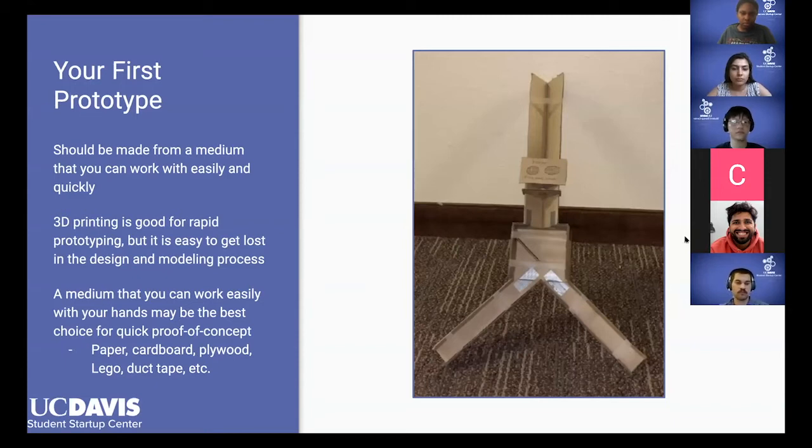This picture on the right is from a student in engineering 3. They actually wanted to prototype their carrot sorting machine. So they used a small scale cardboard version. You can see this is the intake for the carrots to drop into. Here, this piece of cardboard represents an ultrasonic sensor that'll detect the distance between the sensor and the carrot, and then subtracting that from the known distance between the sensor and the track, they can get the thickness of the carrot. And based off a threshold of thickness, this flap will move with a servo, so it can direct the carrot into either of these two other channels so they can be sorted by size.